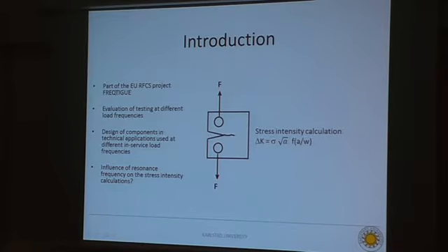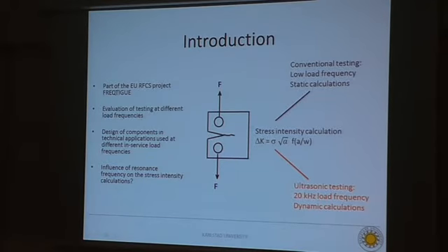One question that we are trying to answer with this paper is if there is any influence of the resonance frequency on the stress intensity calculations. Conventional testing with low load frequency usually requires only static calculations of the stress intensity. But when we are trying to do the ultrasonic fatigue testing with the 20 kHz load frequencies, then we believe that dynamic calculations are required. And what we are doing here, we are doing both static and dynamic calculation for comparison and to see how the difference looks like.